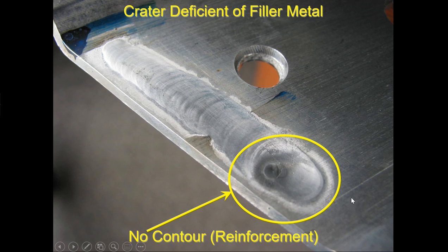But some people took it upon themselves and tried to put a weld on the inside of this. Now, there's actually something that slides down inside of this, so it had to have clearance. So somebody thought, I'll just put a weld on here and I won't add filler metal. And you have to add filler metal, especially because of things like this.